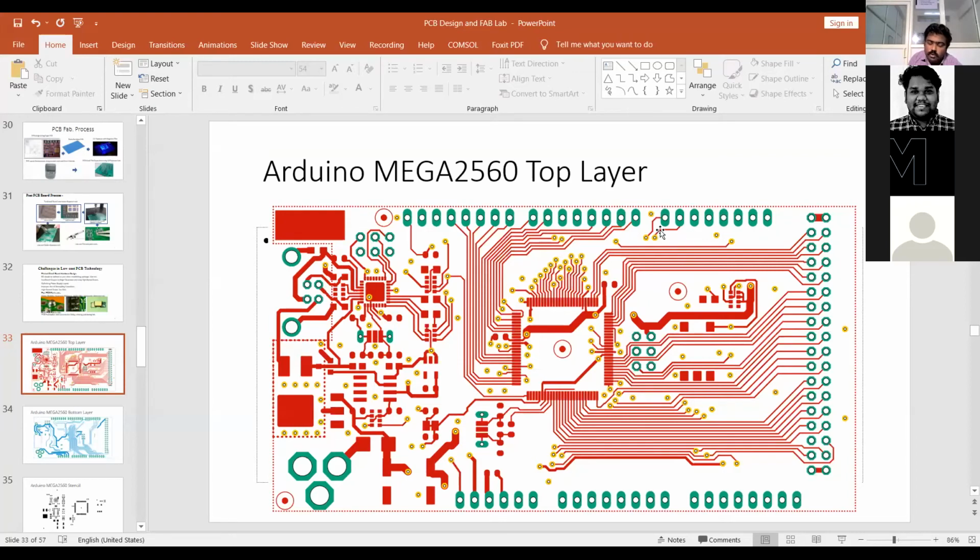So again, you can also go for a prototyper. There is an instrument called a prototyper. I hope you are aware of it. The prototyper does this engraving process with a spindle, with a needle. By rotating it, you can make the board, but it also takes a very long time compared to this one. I think this dual layer will take around 40 or 50 minutes, so that itself takes more than 1.5 hours.